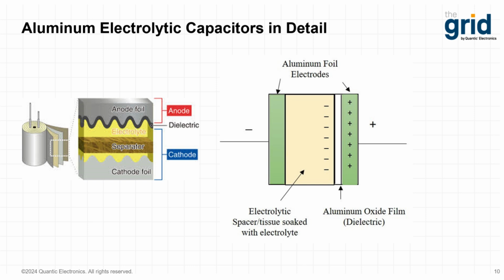Aluminum electrolytics typically have a capacitance range of 0.1 microfarads to 2.7 farads, and voltage ratings of 4 volts to 630 volts. And in some unique cases, they can go a little higher. Some applications of aluminum electrolytics include smoothing, filtering in switch mode power supplies, coupling and decoupling, energy storage, timing and delay circuits with a large time constant.